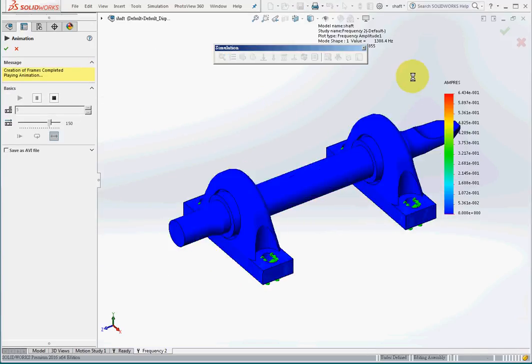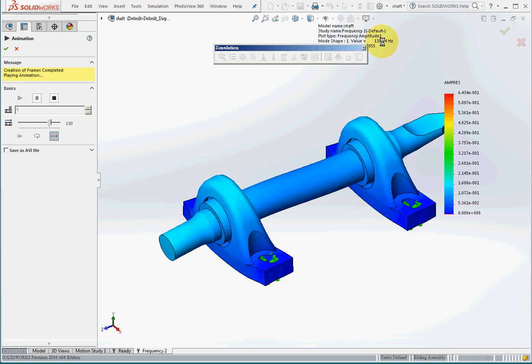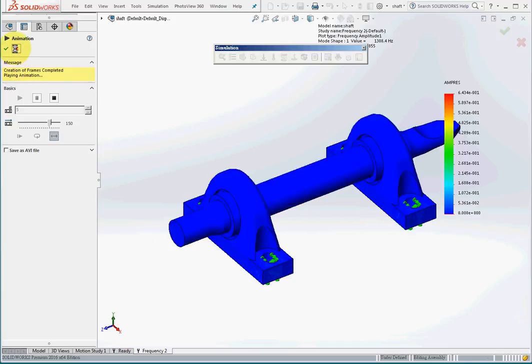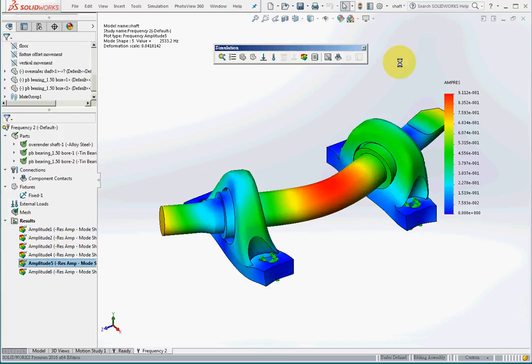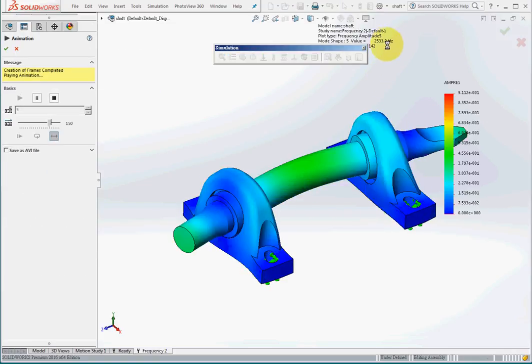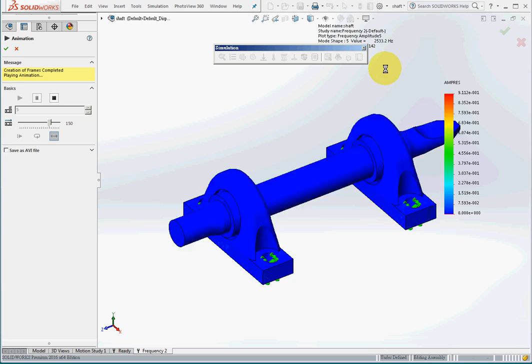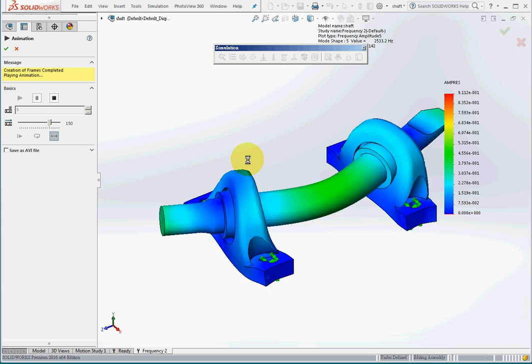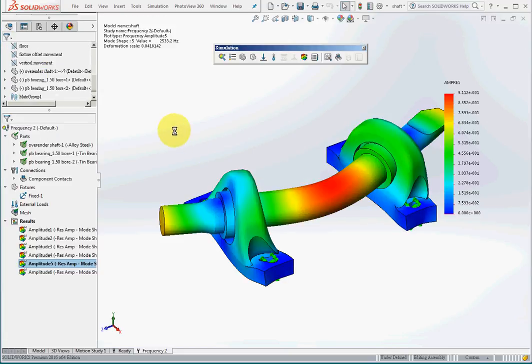Each mode has a distinct frequency and mode shape. For example, in another mode, the mode shape corresponds with the frequency. The frequency is the eigenvalue of the system, and the mode is the eigenvector. So this is the modal analysis. And in part 2, we'll talk about what happens if we place a load on a natural frequency analysis.